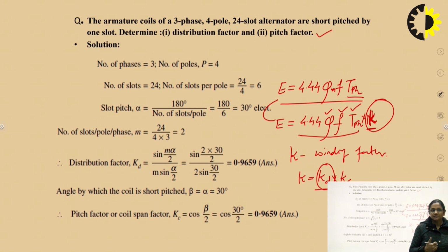If winding is not the distributed one, but the concentrated one, then all the turns of a coil side would be in a single slot on one side, and likewise the other side turns of the coil would be occupying their place in the second slot. So, to accommodate one phase winding, we would be having only two slots. One to have one coil side and the second to have the other coil side of the same coil. If the concentrated winding is used, then the total induced EMF is the arithmetic sum of the induced EMF in all the coils. In case of transformer, the winding is the concentrated winding.